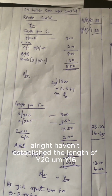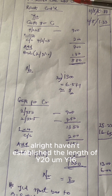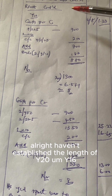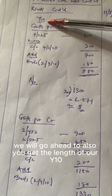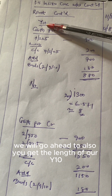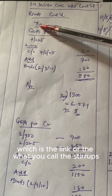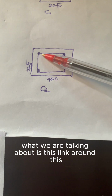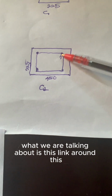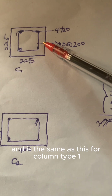All right, having established the length of Y20 and Y16, we will go ahead to also get the length of our Y10, which is the link, or what you call the stirrup. In this case, what we are talking about is this link around this, and it's the same as this for column type 1.